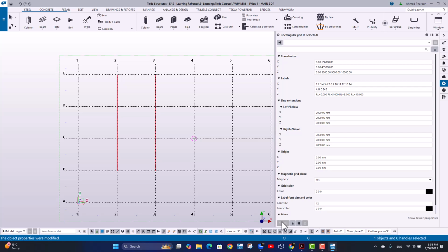So if I have a building, I can use these magnetic grid lines to go through the building. For example, in precast, we have walls here. If I need a smaller building, I would shrink the grid with a magnetic grid. It will be fantastic, right? No, that's not right. Why is that? Because some of the panels are not actually located on a grid.